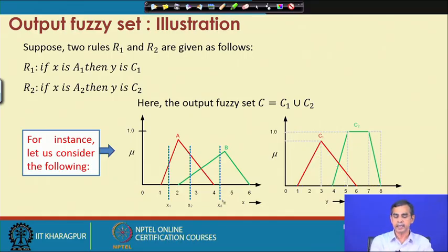Now, the next is x3, which is basically only this one. A does not satisfy, this means this rule does not fire, but this rule fires in this case, and then we can see this part. So for this rule the rule strength will be this one, that means this is the fuzzy output. So we have some idea about how, for the given rule or set of rules, the fuzzy output will be. Geometrically, a fuzzy output is basically a geometrical shape, a portion like this or a curve. So this is also a fuzzy set. We have to obtain the crisp value from these fuzzy sets.